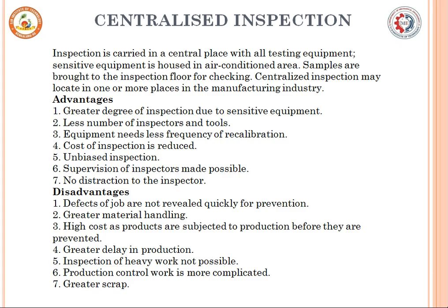Once the part is produced, he's going to inspect and give the parts, because the person who manufactures will be able to sense if there is a deviation in the production process. If inspection is done, he can correct it immediately, so that later inspection is minimized. When we do centralized inspection, when it comes to the assembly at last, we need not inspect the parts, we can assemble directly. So what are the disadvantages of such a job?